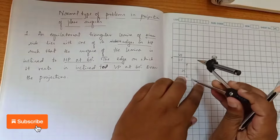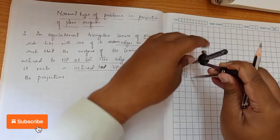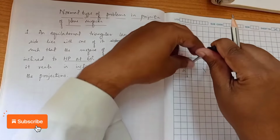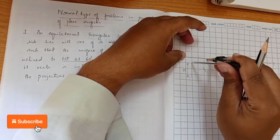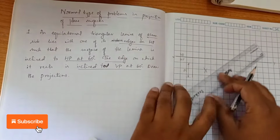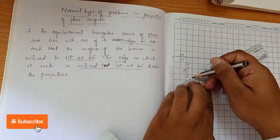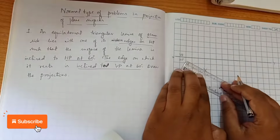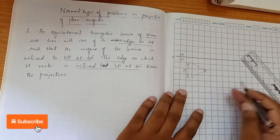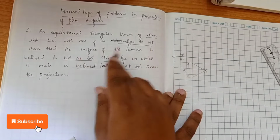Now using the compass we know how to construct a triangle. I'm going to measure the same 25 dimension. I'm going to cut the arc from these two positions, keeping the compass at this point. After cutting the arc, you can join here. So this is the first position, right? An equilateral triangle of dimension 25 resting on the HP plane.